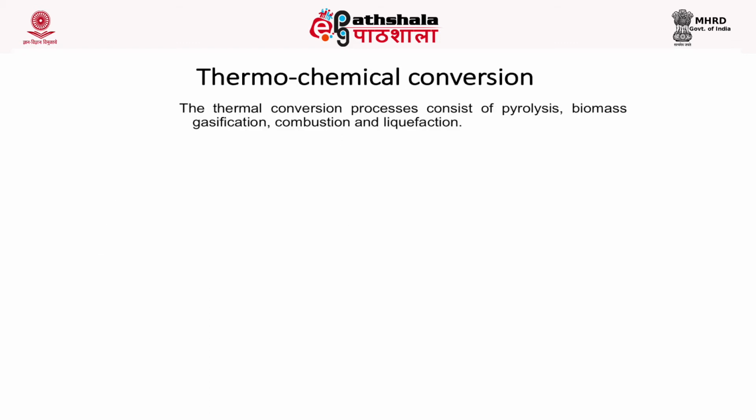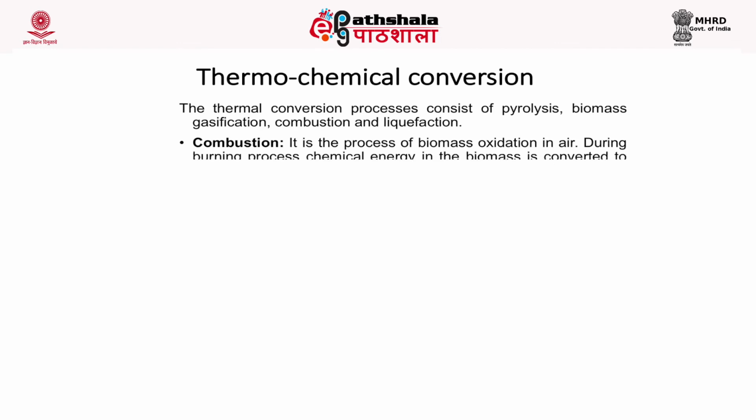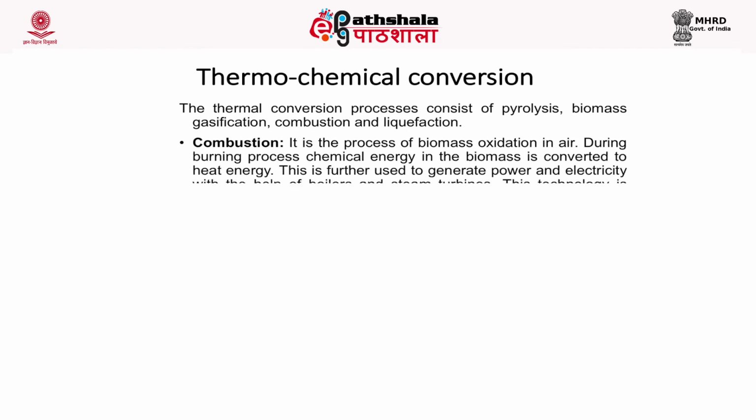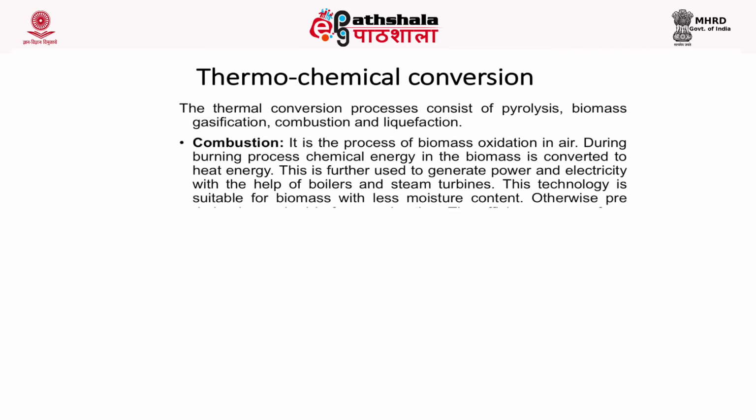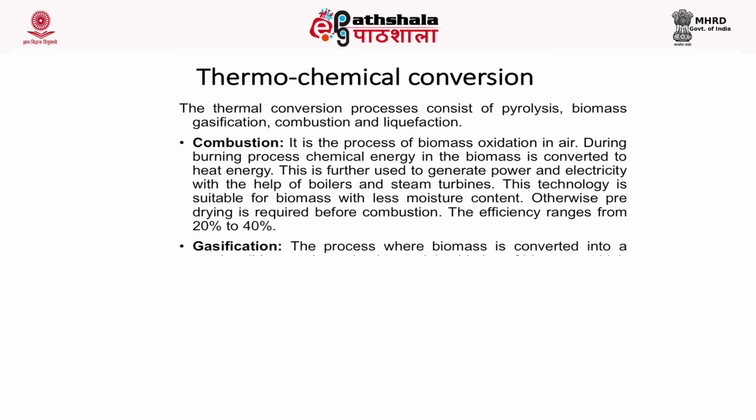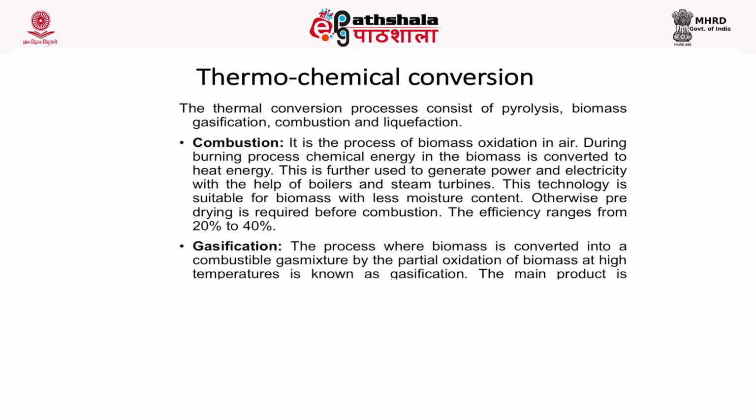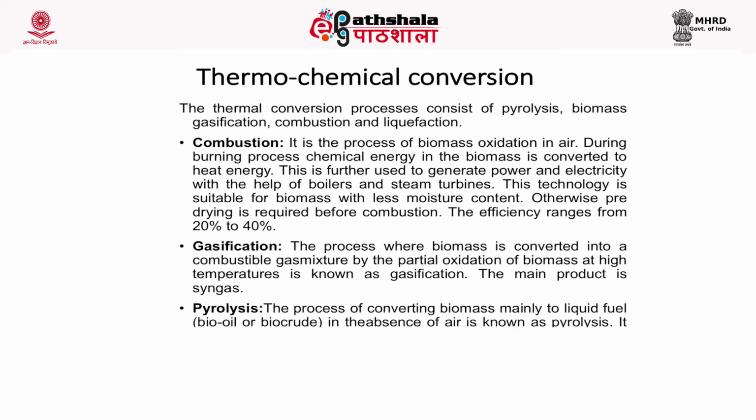The thermochemical conversion processes include pyrolysis, gasification, combustion and liquefaction. Combustion is the process of the biomass oxidation in air. During the burning process, chemical energy in the biomass is converted to heat energy. It's further used to generate power and electricity with the help of boilers and steam turbines. This technology is suitable for biomass with less moisture content. Otherwise, we require pre-drying before the combustion. And the efficiency ranges from 20 to 40%.